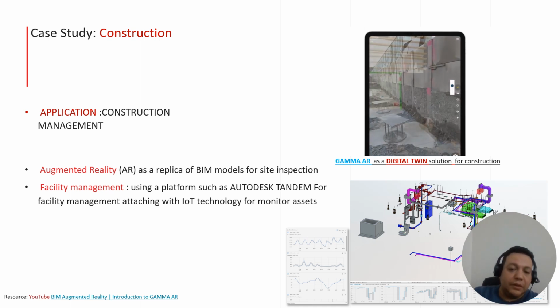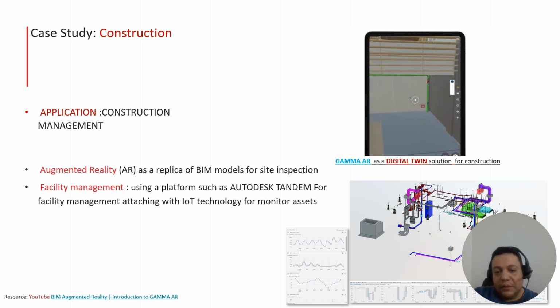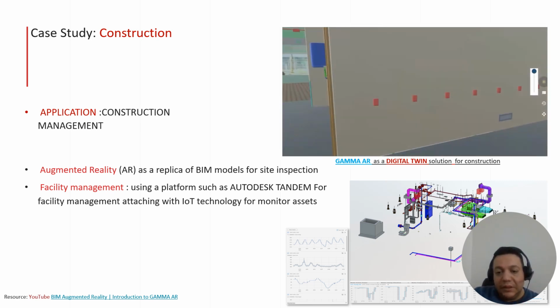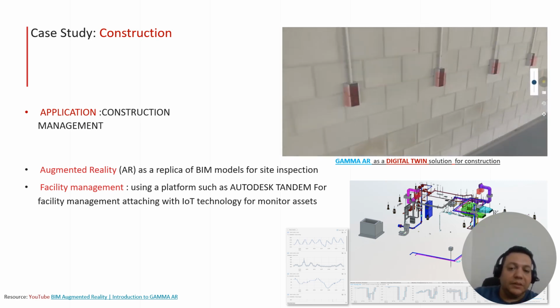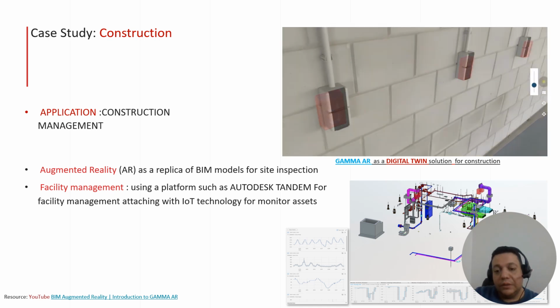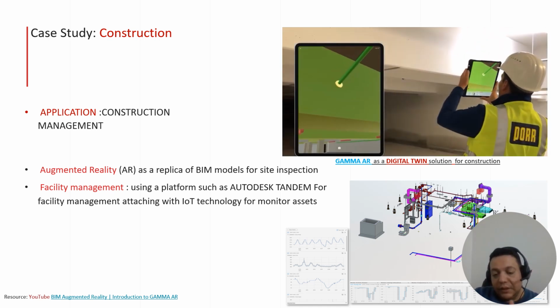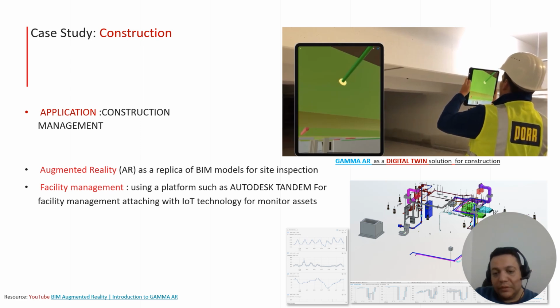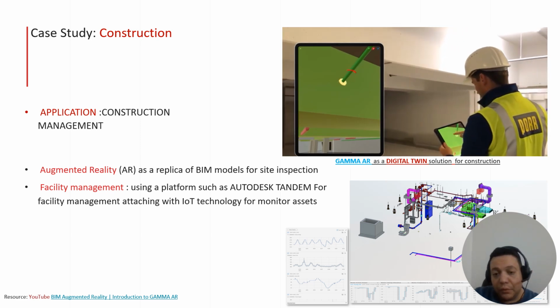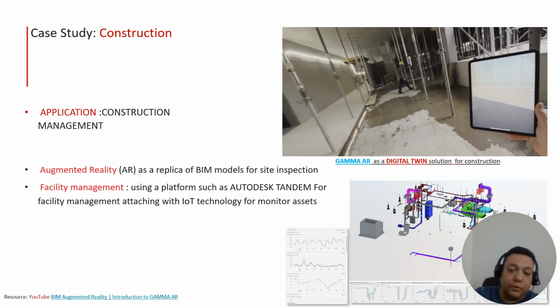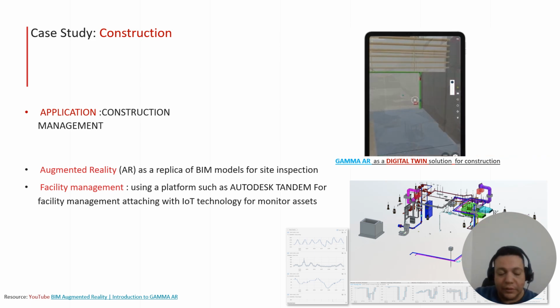Through that, we can plan our work on site, checking, for example, openings that will be needed for MEP, checking what supports or accessories will be needed for the next MEP work, and prepare our work for site in the same way, checking if there are flaws that need to be rectified before it goes to site and we have rework.